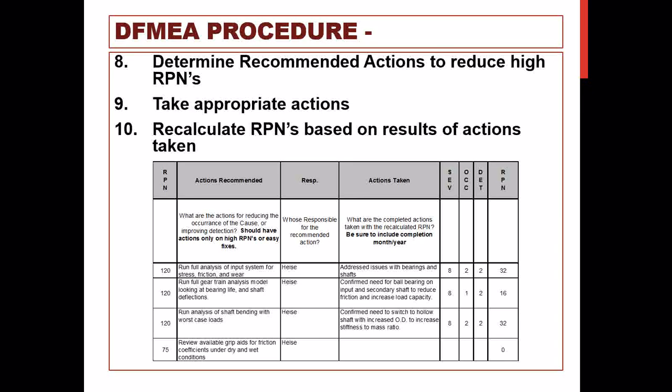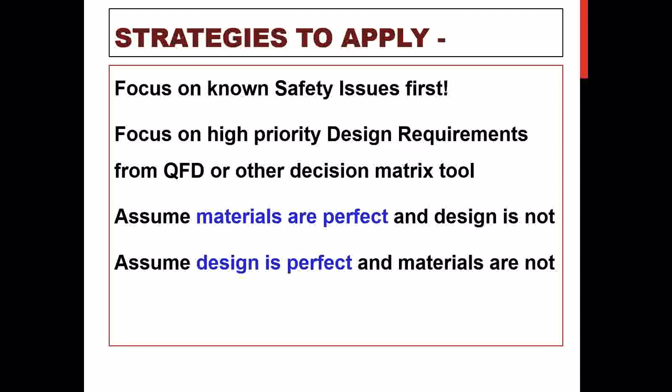Well, we still have the primary function of the product, but it's not operating well. So that's not as severe. We've ranked it as a 5. Occurrence level, again, is ranked here at a 5. And our detection level with doing material testing, we set as 3, so we get an RPN of 75, and so forth.